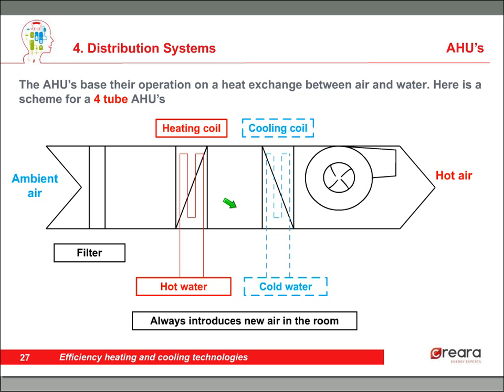Well, that is because, for instance, in Spain, there are places, especially in the south, where in winter, if you have a building that has two facades, one to the south and another one to the north, in the one heading to north you're going to need heating, but in the one heading to south you're going to use cooling probably, because the sun is hitting through the window and you just need cooling. So that's why this air handling unit exists.